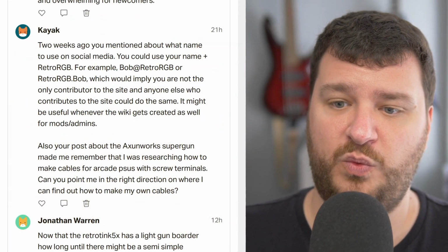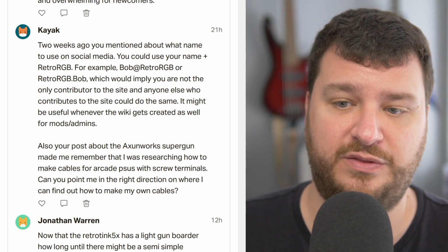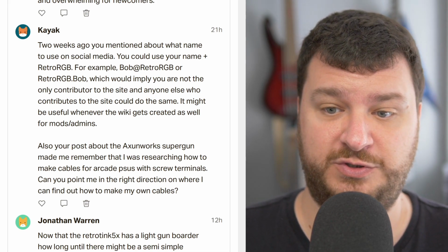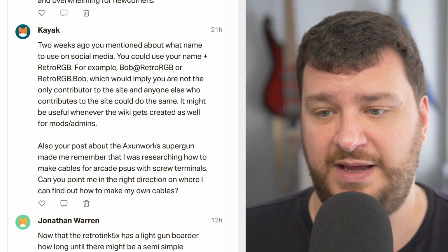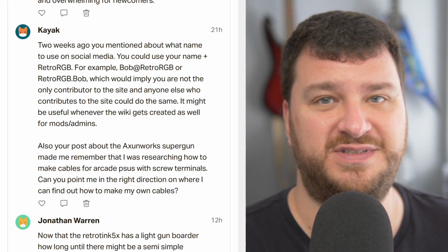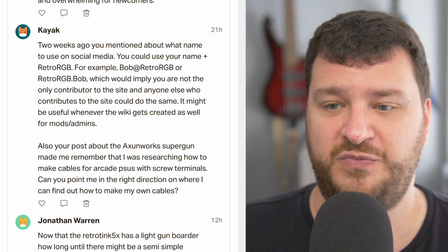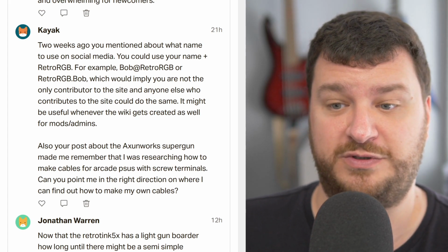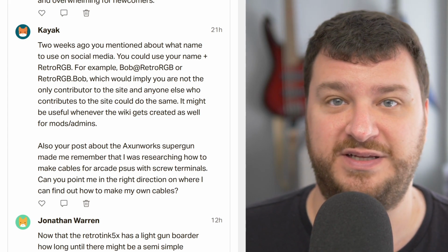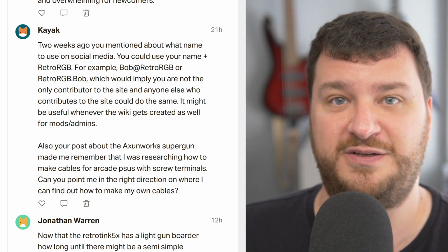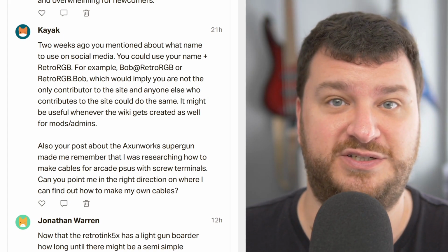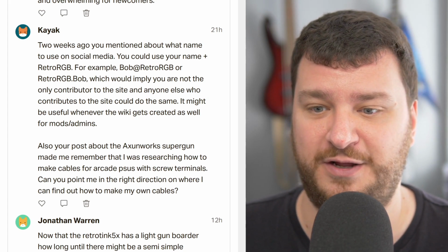Kayak wants to know where they could get information on how to make their own cables. I guess the question was sparked by the ActionWorks Supergun review that I did. And it really depends on exactly what your source and target device is going to be. So in the case of the ActionWorks Supergun, I would say if you're looking for SCART, get a VGA to BNC cable, cut the ends off, wire that into a SCART connector, wire in an audio jack, and then make sure that there's a resistor on the sync line, and you're done.